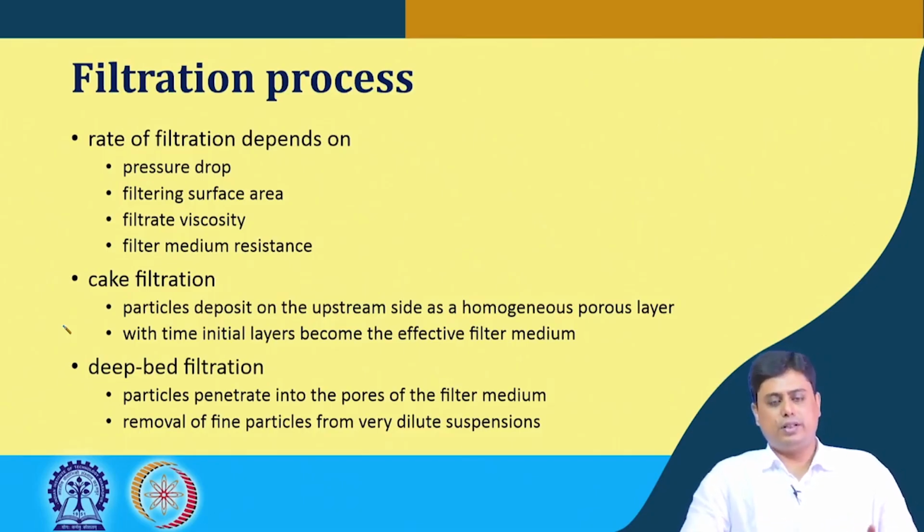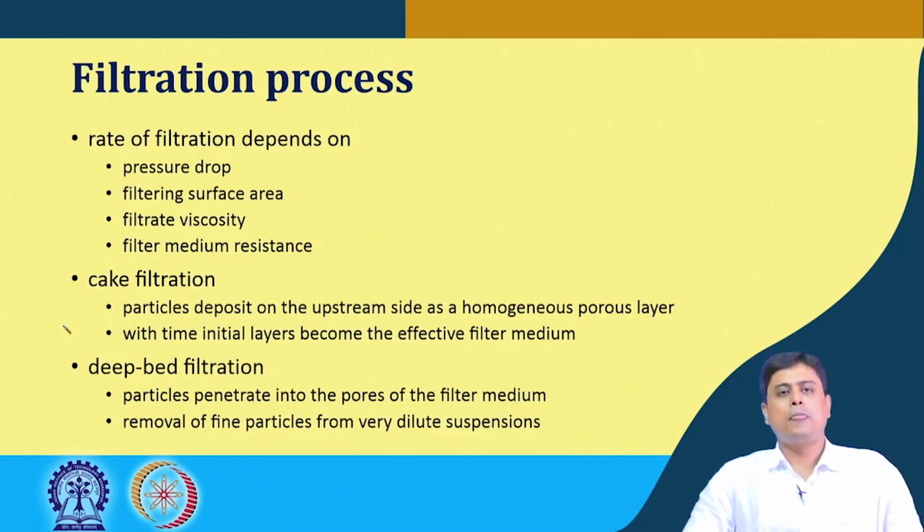So the rate of filtration, the rate at which this process can occur, depends on several factors, and one of the primary factors is the pressure drop across the downstream side of the filter media to the feed entering portion or the suspension top area.